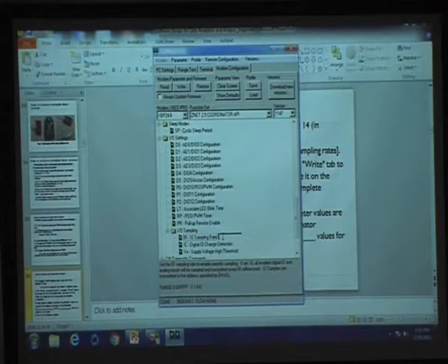Remember, whatever values we are giving to these register parameters are basically hexadecimal values. 14 is equivalent to 20 milliseconds. 20 milliseconds is again equivalent to, what will be the hertz value, please? 50 hertz. So 50 hertz is the equivalent sampling rate at which you are trying to transfer the data here. So you are just putting the 14 value here.